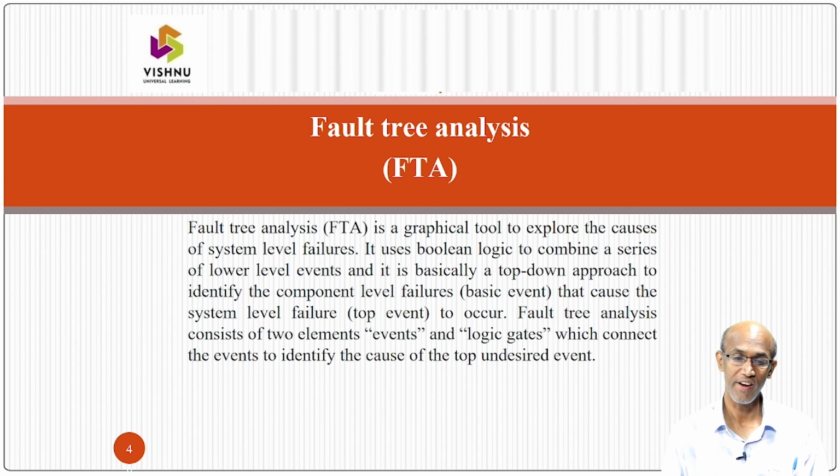Next one is fault tree analysis. Fault tree analysis is a graphical tool to explore the causes of system level failures. It uses Boolean logic to combine a series of lower level events, and it is basically a top-down approach to identify the component level failures that cause the system level failure to occur. Fault tree analysis consists of two elements, events and logic gates, which connect the events to identify the cause of the top undesired event.